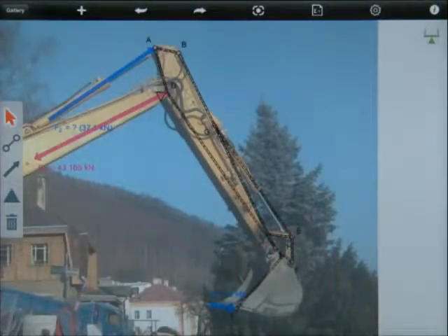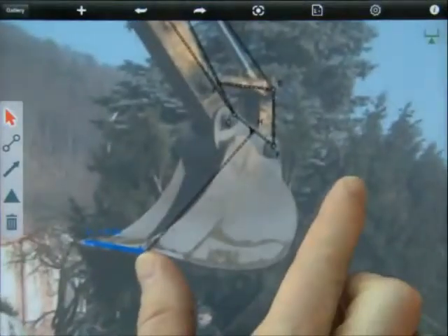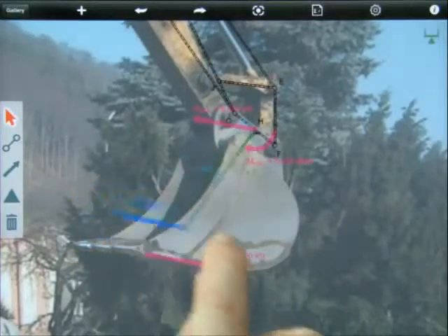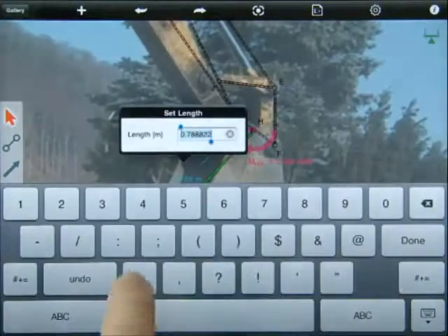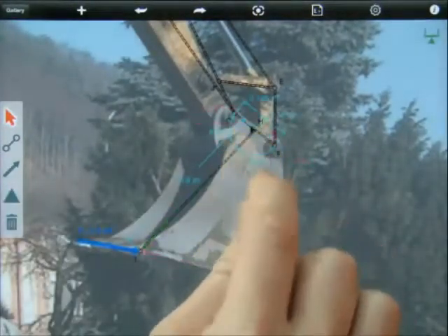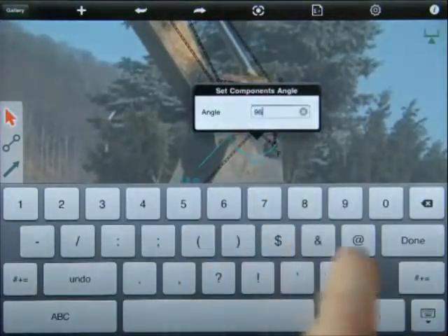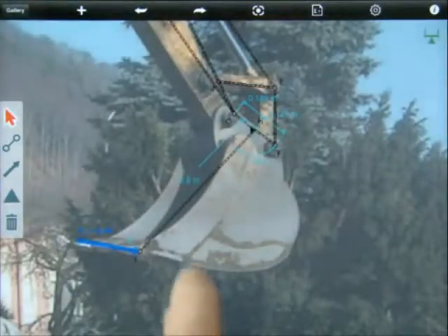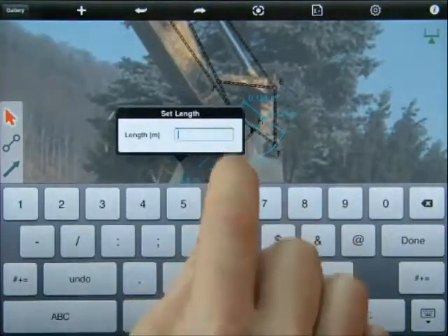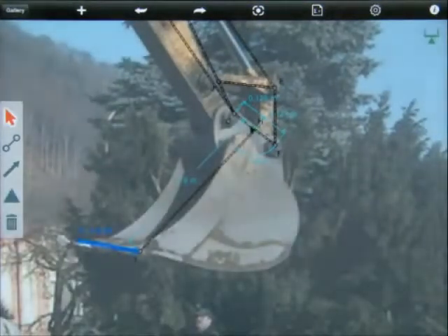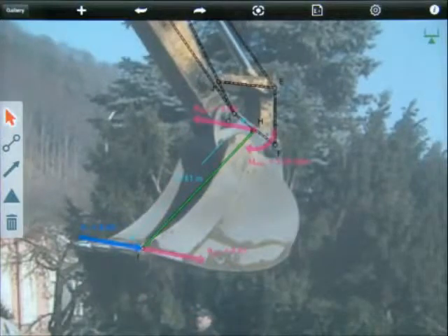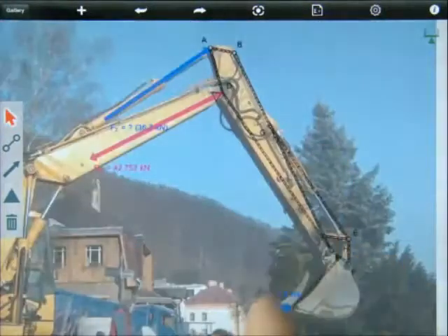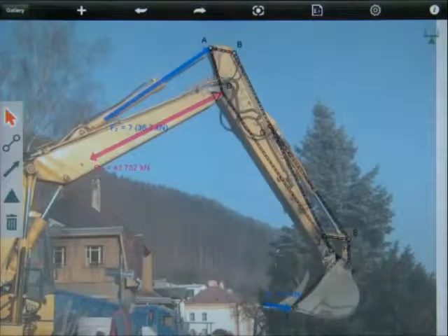When no members are displayed, the vectors by default are at the supports. You can drag members to change their length and angles. Alternatively, you can input a precise value. The reaction calculations update automatically. Once you enter a precise value, that dimension is frozen and indicated by an asterisk. To unfreeze the dimension, simply drag the segment or clear and enter and tap done. You can toggle between your combined force vectors and component vectors.